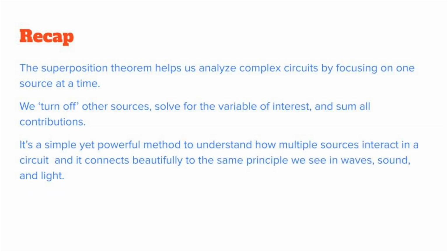The superposition theorem helps us analyze complex circuits by focusing on one source at a time. We turn off other sources to solve for the variable of interest and sum all contributions. It is a simple yet powerful method to understand how multiple sources interact in a circuit, and it connects beautifully to the same principle we see in waves, sound, and light.